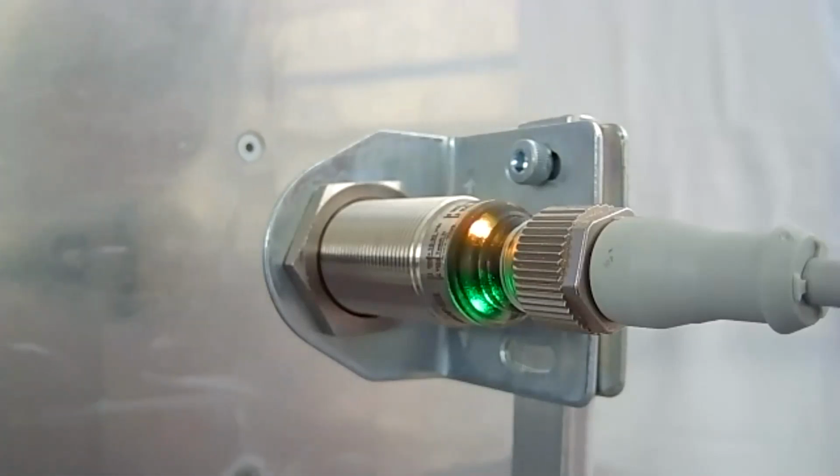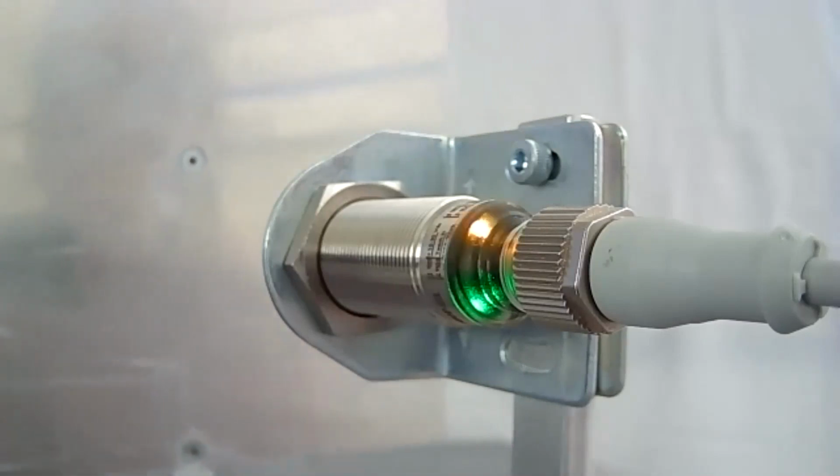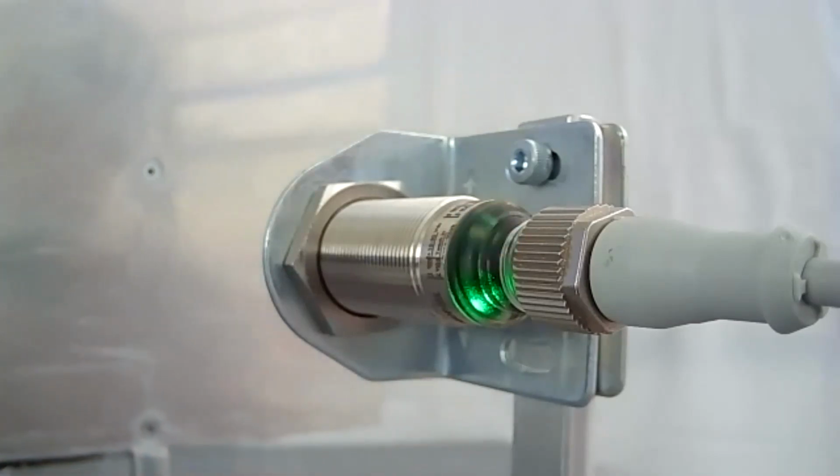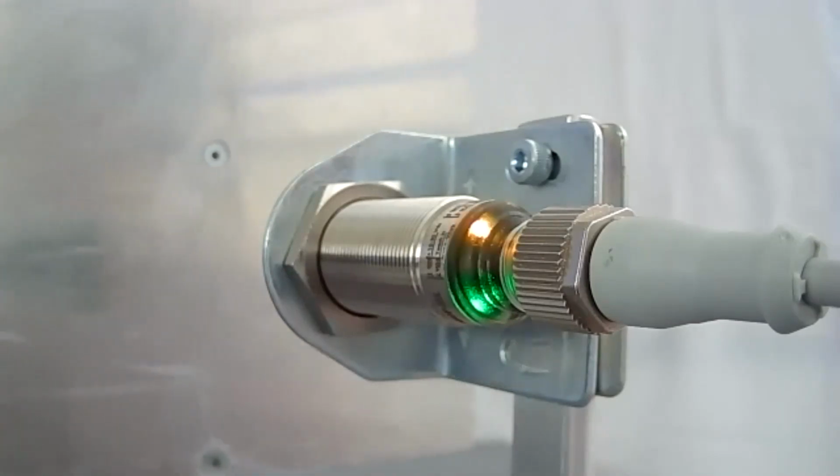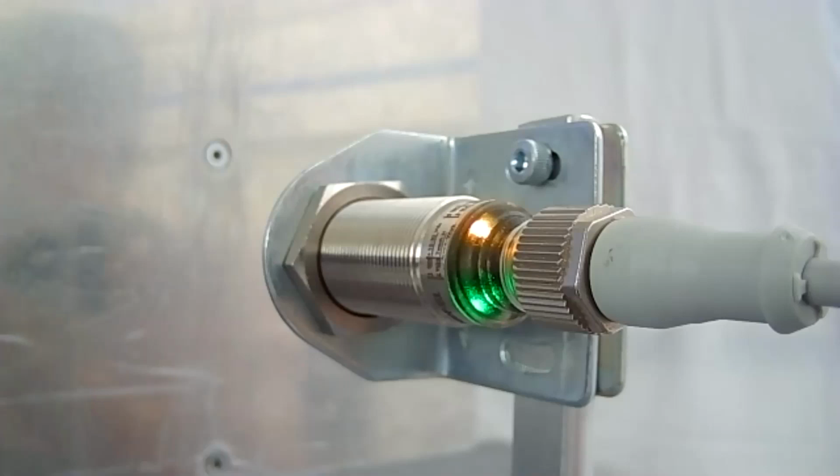Please remember always, once you have set your point, to connect the white wire to the other pole, because otherwise this white wire would act like an antenna, catching all the electrical noises of the environment and creating some interferences, some disturbances to your sensor behavior.